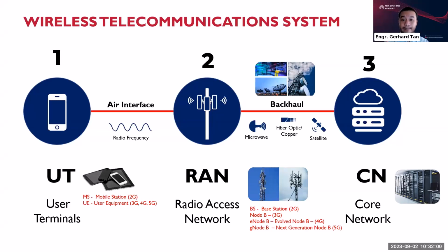Take note that microwave links are also sensitive, especially when there is a heavy rain. Fading is something that we cannot avoid, but we can intervene. And we can address it by delivering redundancy, or diversity.